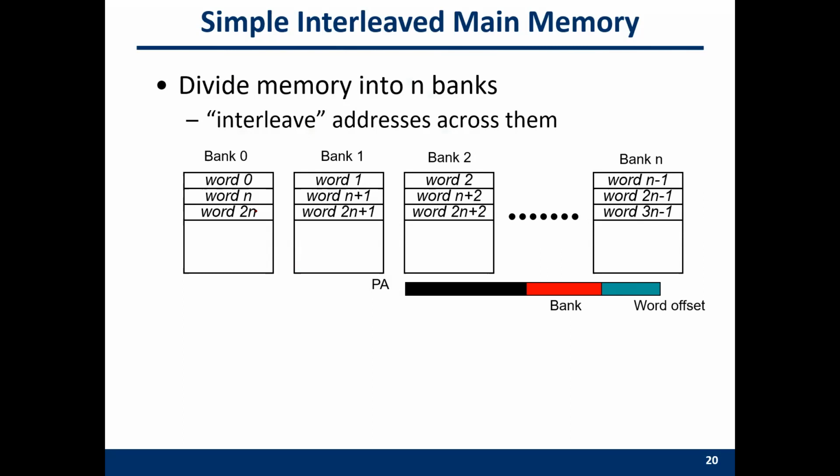And we also have the concept of a bank in the DRAM. A bank is a piece of DRAM which can be independently read and written. This is the physical address, this is your 64 bytes, or your memory line size. You can store your data with a layout like this: word 0, word 1, word 2, and then word n-1.